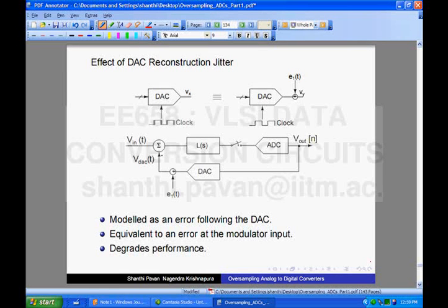Oh, please note that this jitter is a very, very small number. So the argument he is making is that isn't clock jitter a problem also, because it kind of varies the noise transfer function of the loop, since you can think of it as a change in delay, but this delay will be very, very small compared to the period of sampling. If this jitter becomes comparable to the rate at which you sample, alright, then you're in deep trouble. Okay, so that's not what happens in practice.